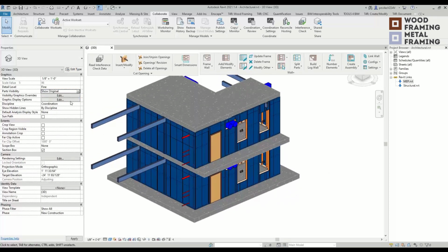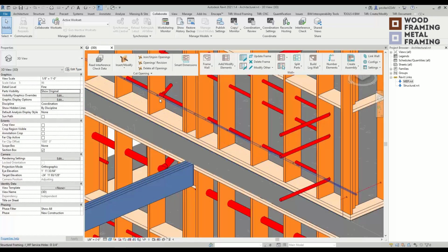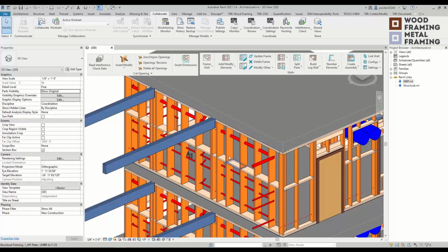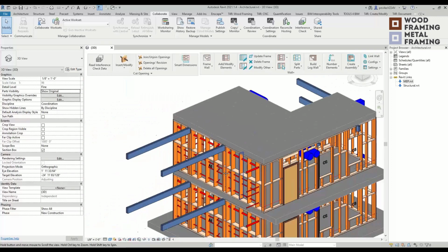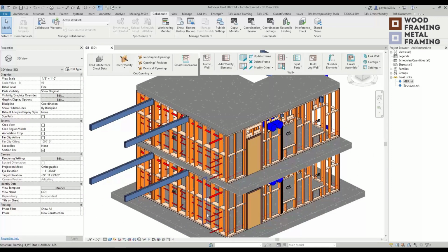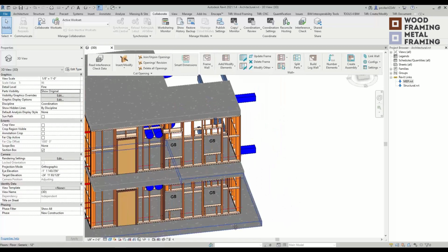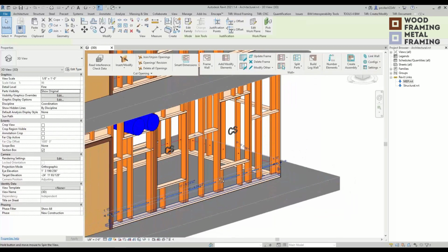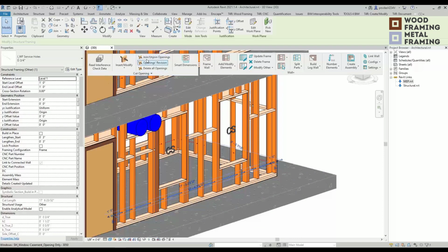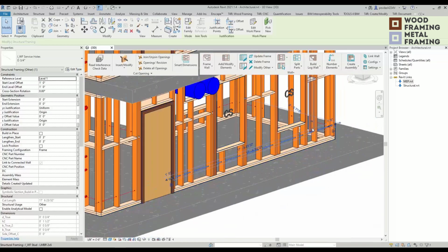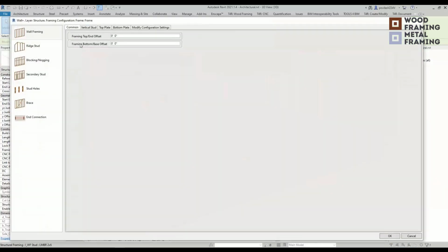Okay, so what I've not yet done is produce openings for each stud in the frame, where I have some sort of pipes running within the frame. And before I do that, I want to notice that you can produce openings in configurations as well. So you don't necessarily always have to run cut opening or draw openings by hand, like walls, doors, opening families. So like this penetration hole, if you go to configurations, well, in this case, I'm going to modify frame for a quick result.